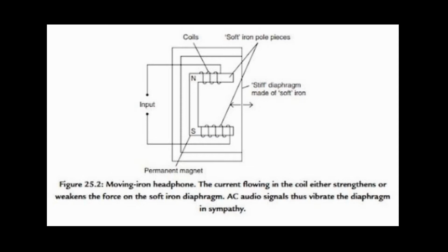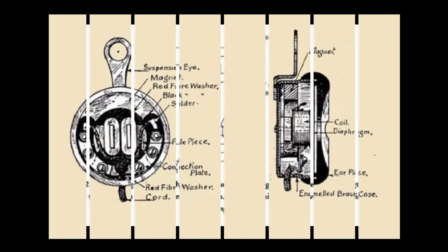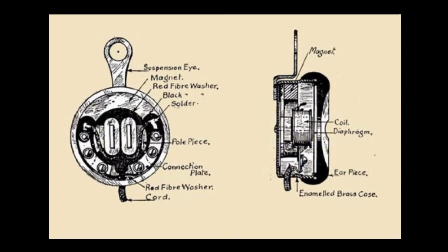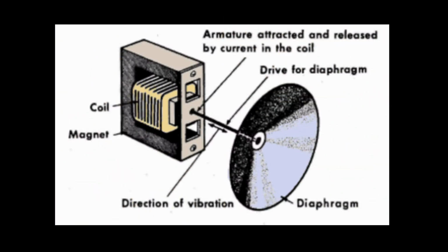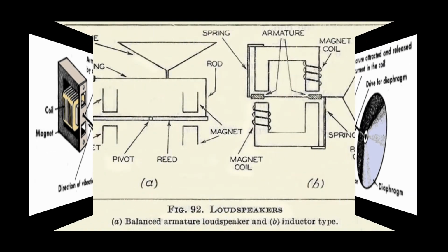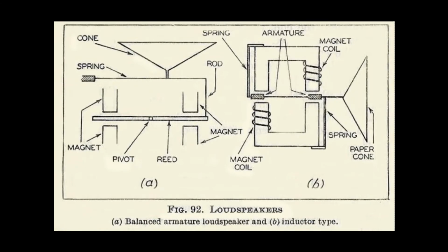The requirement for high sensitivity meant that no damping was used, so the frequency response of the diaphragm had large peaks due to resonances, and it resulted in acceptable voice quality but very limited musicality. The moving iron driver is another type. In this design, the moving permanent magnet is attached directly to a plate of metal, celluloid, or a paper cone diaphragm. A large fixed coil would be wound around the outside, and this was an early way to drive more power in larger structures, such as in horns and paper cone loudspeakers.